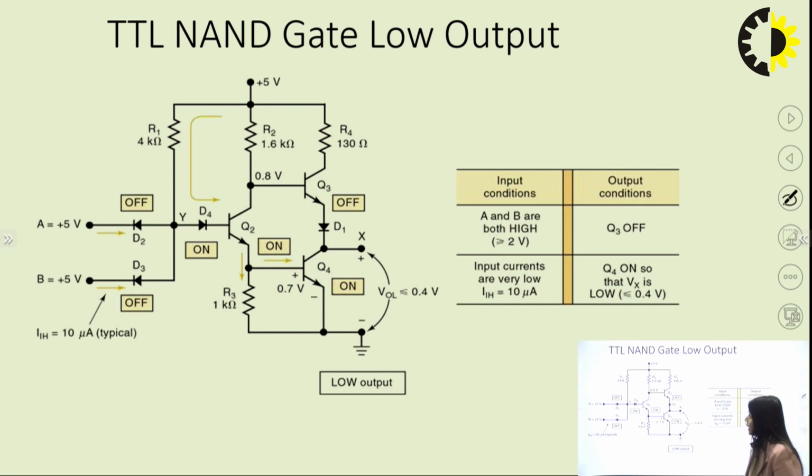See, I have removed this particular transistor. These two diodes are as well, right? There is no problem at all, and Q2 becomes on. Q2 becomes on, and while Q2 is on, it will definitely turn on the Q4. Please repeat my words that if Q2 is on, then output will also be on, and if Q2 is off, then Q4 will be automatically off. So Q2 and Q4 are connected with each other.